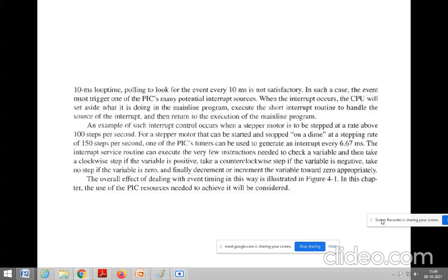That interrupted device is nothing but any external device which is seeking a request with your PIC microcontroller. So the PIC microcontroller will stop doing that main program and execute that interrupt subroutine program. After completing the interrupt service, it will return back to the main program for execution.